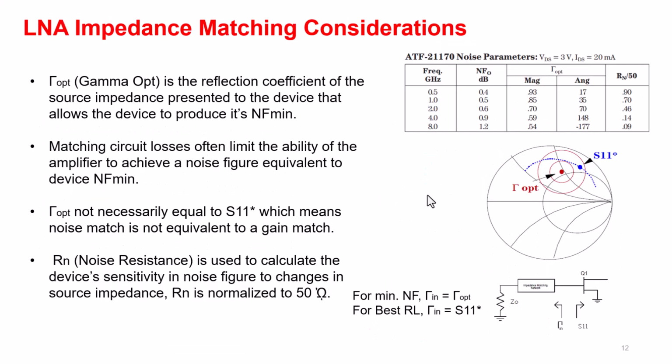Now, when it comes to impedance matching, remember earlier we discussed about the noise figure should be then balanced with impedance match and the gain. So here is why. When you have read the theory about amplifier or impedance matching, we have often spoken about complex conjugate matching, because that gives you the maximum power transfer, hence appropriate.